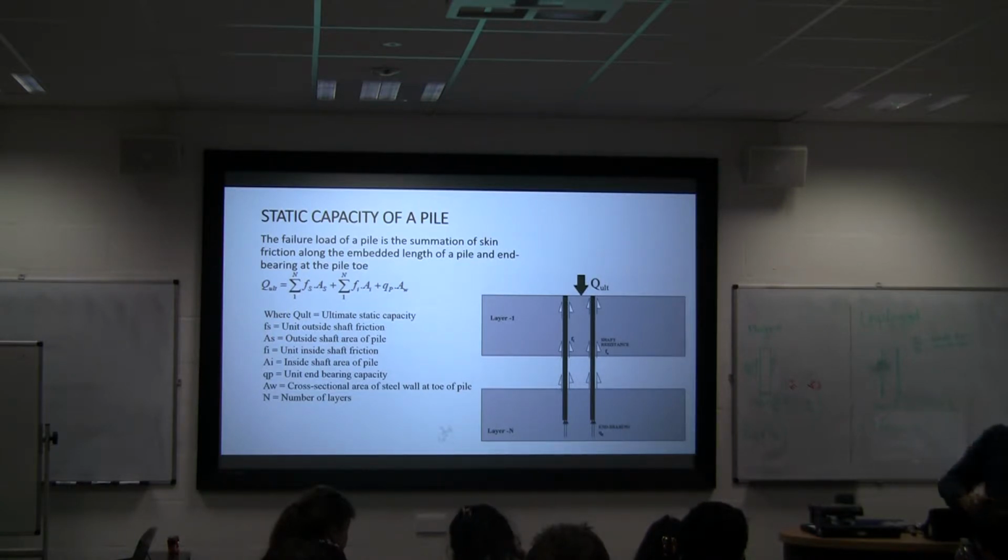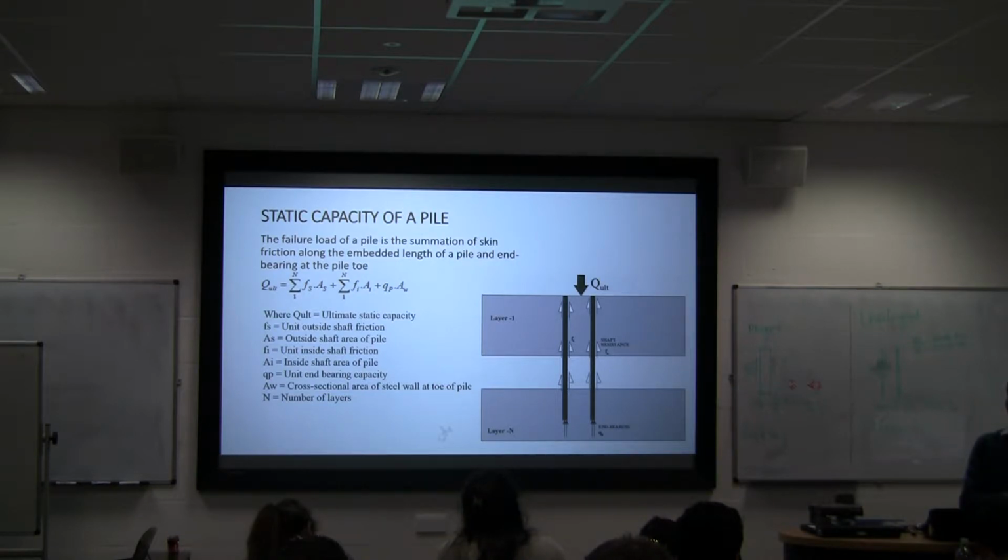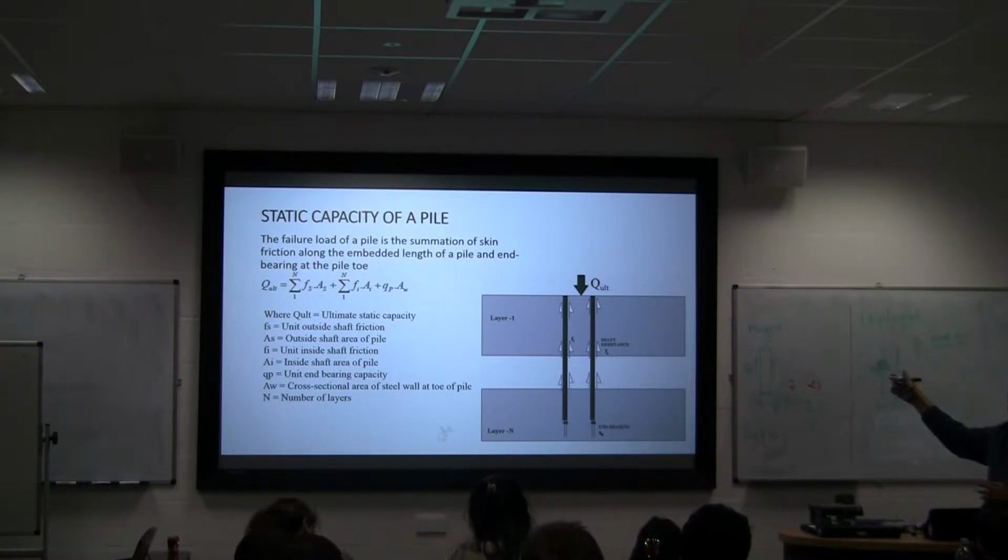When you drive, it drives unplugged. So you put the pile in place, you leave it there for 6 months, because after the piling, you then start to bring the jacket, you put it there, you build it, it takes 6 months to build. In those 6 months, the soil consolidates. When you apply the load, it behaves plugged. So when you drive, it acts like an unplugged pile, but when loaded it acts like a plugged one. It's very complex. So when you drive it, you're driving with the soil getting in.